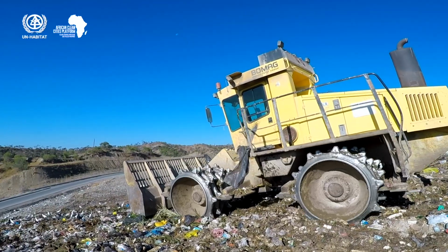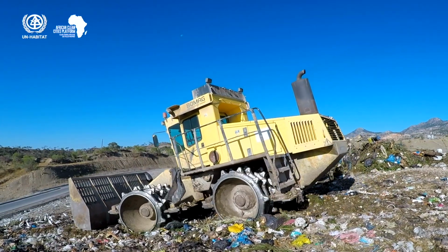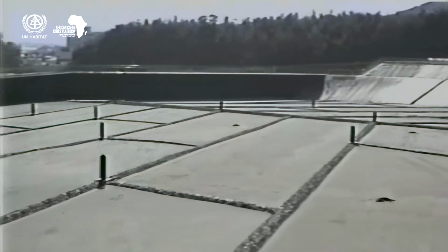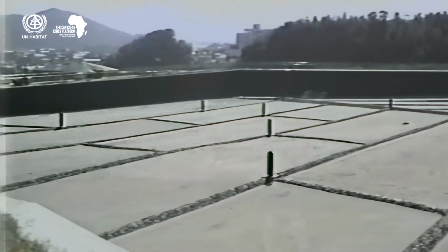Additionally, if embankments are constructed first and landfilling is conducted after that construction, local people won't see waste being dumped and the operation of heavy machinery. So far then, this looks much like any other controlled landfill, apart from these raised channels and what looks like chimneys. These are the leachate pipes and gas venting systems and are what make it a semi-aerobic site.